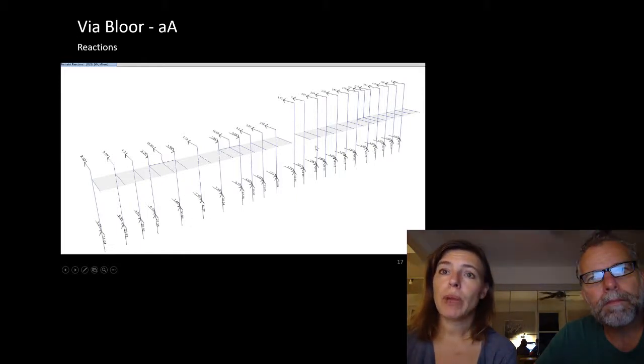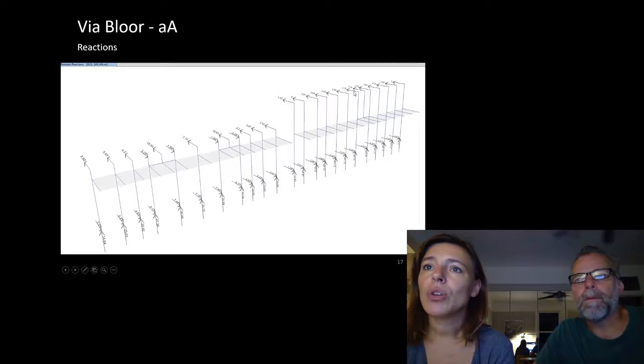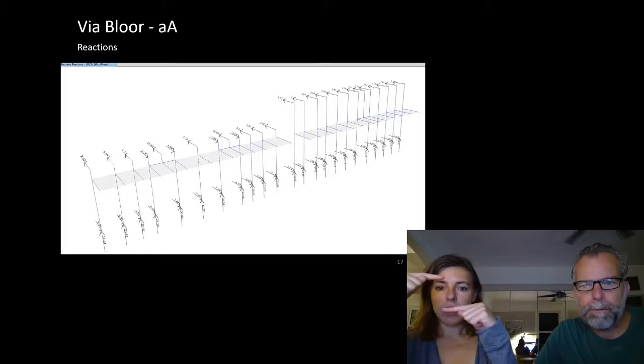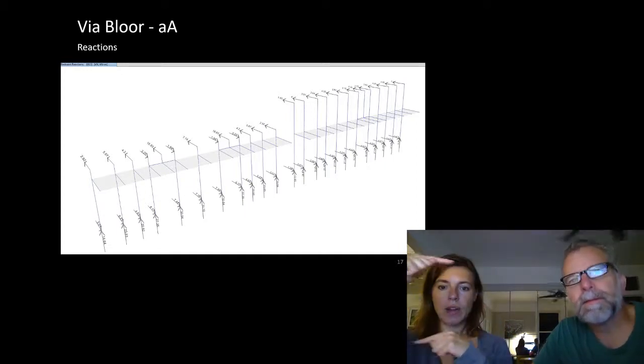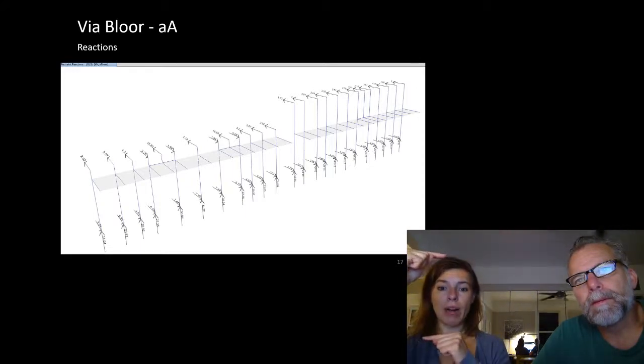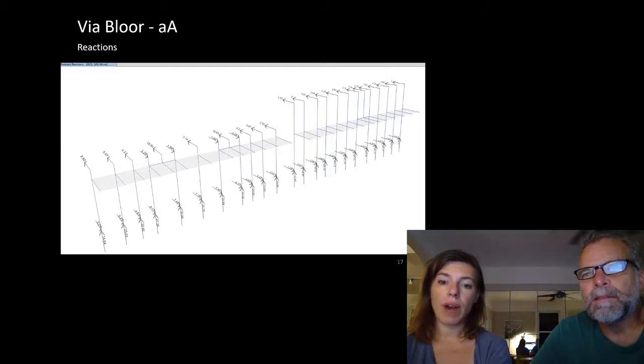So this is a much bigger column, but look at these reactions. Let's not look at the end conditions, but we vary from about 3 to 18. But over here, we vary from like 2 to 5 kilonewtons. It's because this was our couple on the short canopy, and this was our couple on the long canopy. So we've extended our moment arm for the resolution of our canopy.